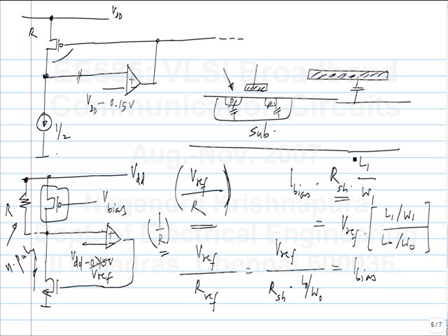So that's a very common way of propagating bias voltages on a chip. This kind of bias you use in the flip flop, and you can also use it in the transmit driver, because you have load resistances that are on chip. Let's say we assume that it's on chip. In that case, you need to produce reliable, accurate swings, so you need the tail current to have this kind of dependence. Any questions?